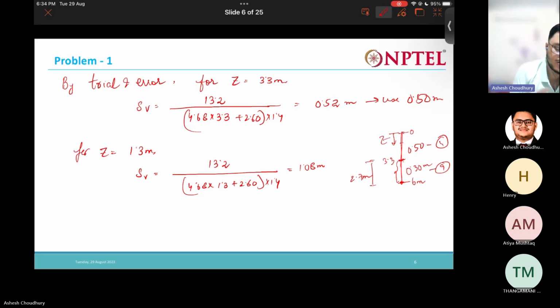So 4.7 meters we have already covered, right? So 6 minus 4.7 is 1.3. The remaining 1.3 meters, we can provide two reinforcement layers at 0.65 meter. So total 9, 10, 11, up to 15. Total 15 reinforcement layers we can provide like that, using 0.65 meters.